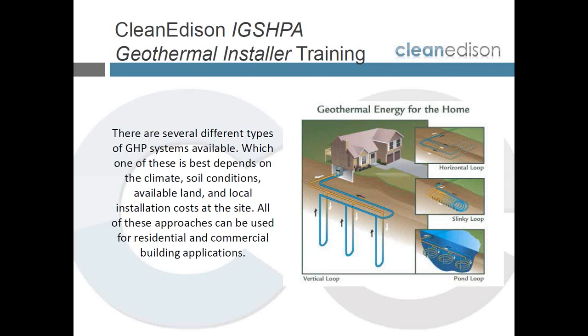You see that the water will circulate by reverse return, first in is last out, and we will be going through all of the manifolding and how to design these process systems. And inside the building, in the basement, you see a circulator pump and a heat pump there that draws the heat out of the ground into the house.